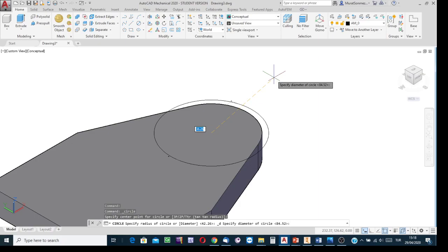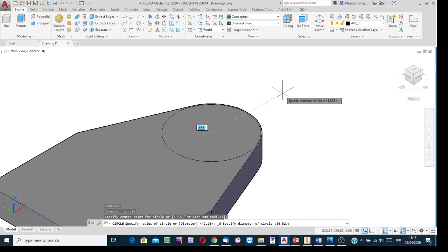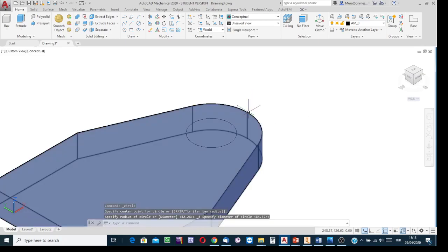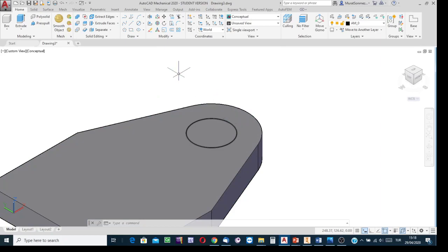Into the box, write the diameter of the circle, or you can indicate the midpoint of this arc to say that it is the point the circle passes through. Which one you like. Indicate this with a click. Since I selected the diameter option, AutoCAD just created the circle in half size.